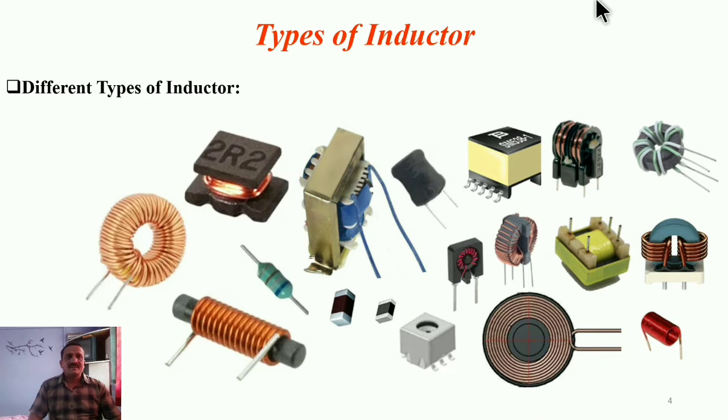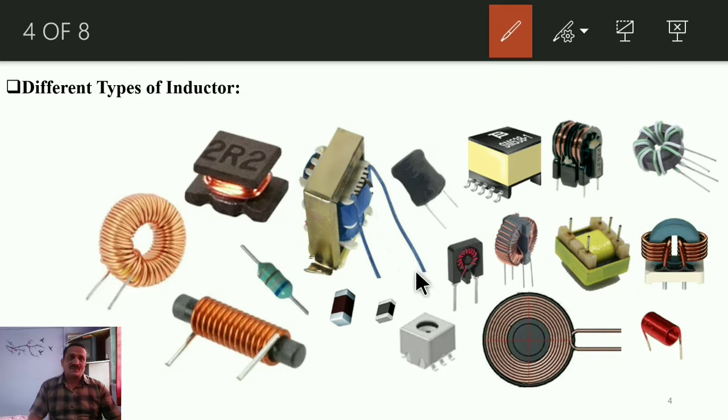So here you will simply observe there is a copper coil wound on various non-conductive materials, like standard bobbins, then ferrite cores in circular as well as square shape or various other shapes, right? According to the required inductance, that is L, the number of turns as well as the gauge of the copper wire is calculated, and accordingly that inductor is formed.